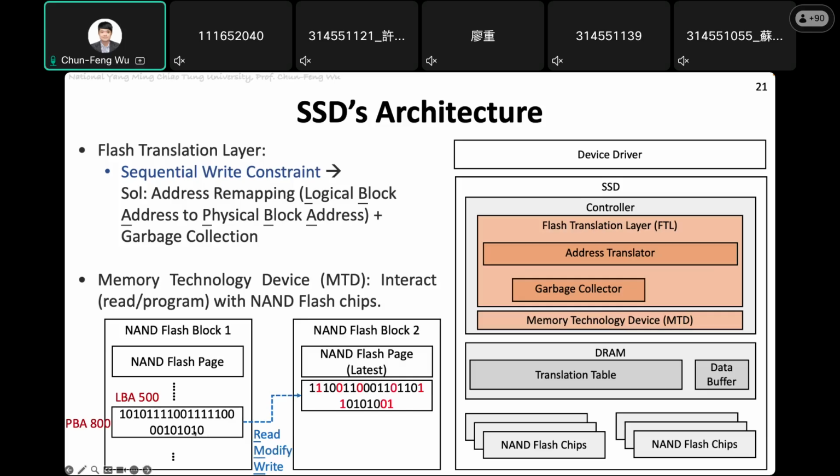The SSD should use out-of-place update. Out-of-place update means we need to read out the full patch and then modify it, like 111011, in DRAM, and then write it back to another available space in a different location. So, for example, if there is a free allocation on the second patch of block 2, you will move it to here. Then what the FTL will store is, hey, your LBA 500 is not mapped to PBA 800 now, because in your SSD, we helped move it to another place.